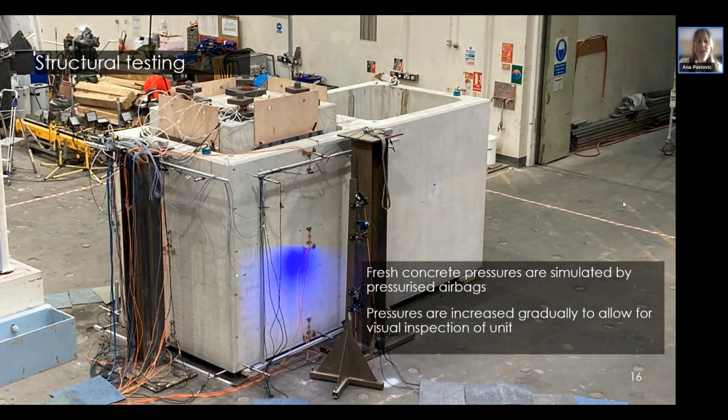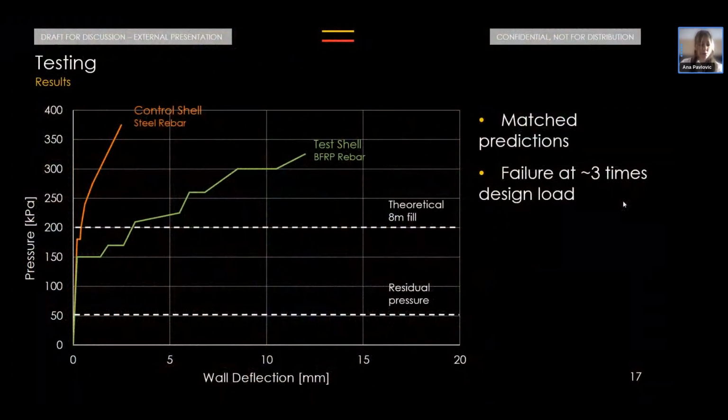The way that they were loading is with 4 pressurized airbags that were simulating the pressure of the fresh concrete on the inside walls of the shell, and the pressures were increased gradually to allow us to inspect the unit and record the results. I won't dwell on the results just in interest of time for now, but you can see here very quickly the comparison between the control shell with steel reinforcement and our alternative shell with BFRP reinforcement.